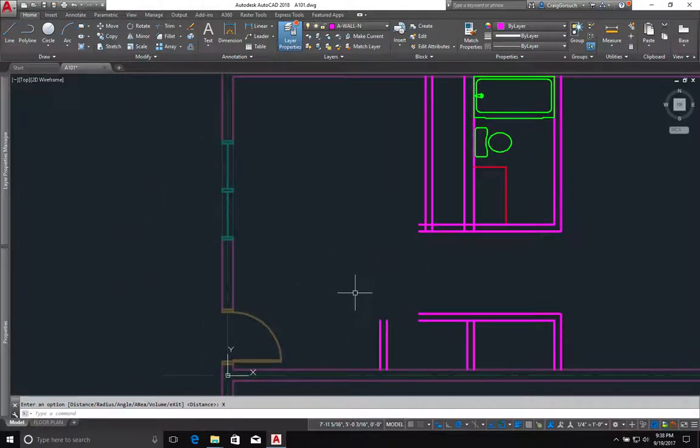Okay, now I'm doing something a little unusual. This point is going to be kind of strange. I don't want to take this wall and extend it all the way across to here. This area right here, that's actually going to be my bedroom in this particular design layout. So I'm going to create an arced, a circular wall, just because I want to. But I still want that 5 foot clear right over here, so I'm going to create a 5 foot circle.